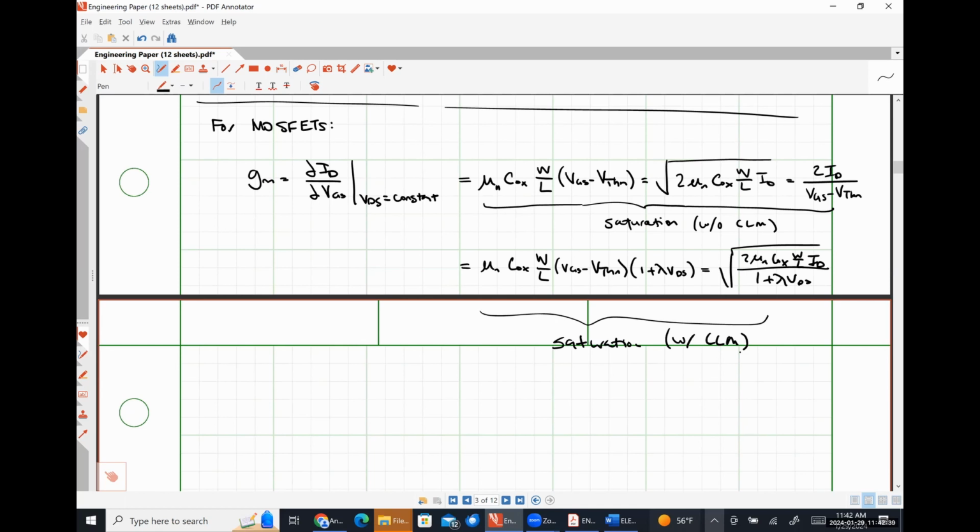Now, we also potentially have to worry about a transconductance due to the body effect. So this guy right here, if we calculated ID, the DC operating point of our drain current with channel length modulation effects already included, it's already buried inside of that effect.